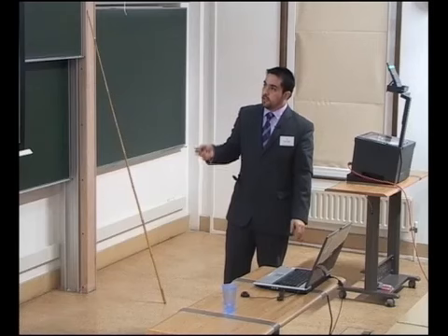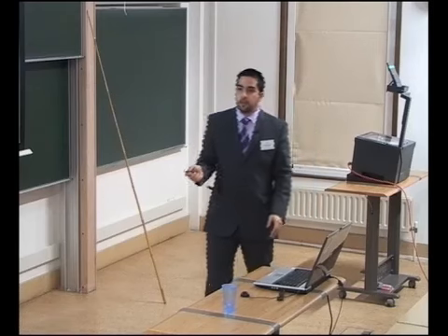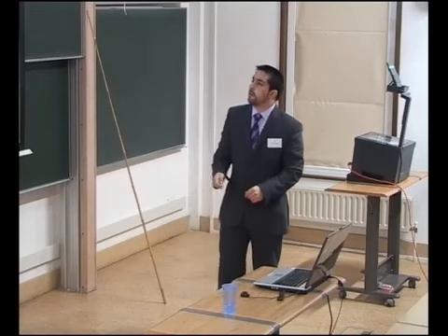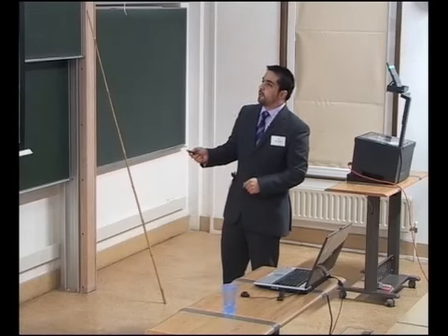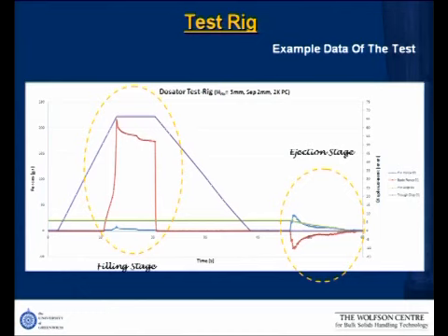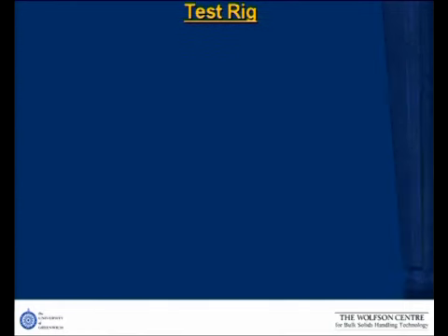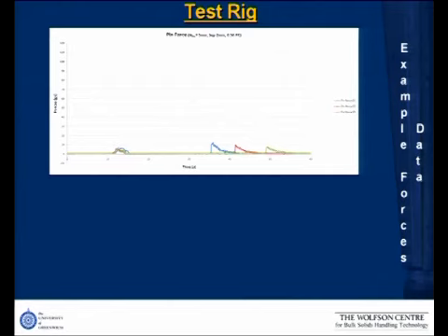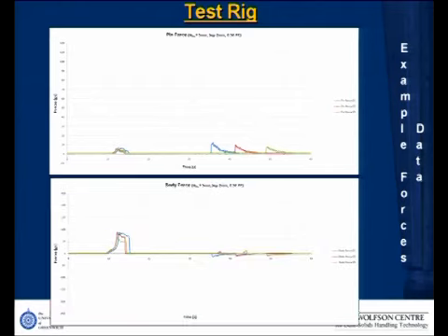As soon as the cavity is full, we get some forces against the pin here, and as soon as we put the trough down, exactly at the same time they disappear. And then here is the ejection force, the pin force, and then here we get a mirror effect from the body of the dosator.